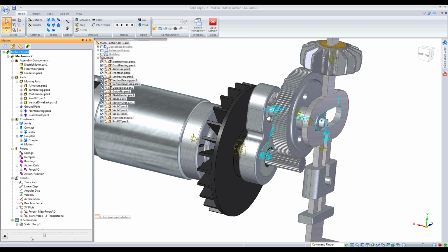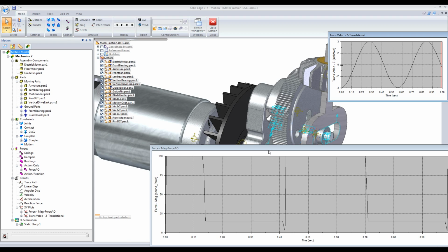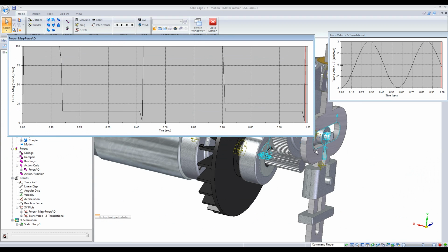During the calculation, the load on the blade, which is 100 pounds as the blade is coming back up when it's cutting, and 15 when it's piercing through the wood, is going to be applied through the mechanism. And we see that the static study that we've done in FEA has been detected. So we will be able to transfer load that way.